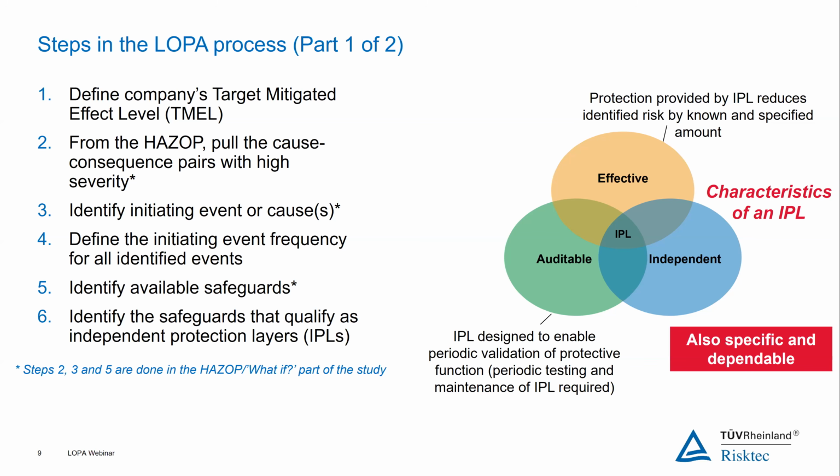Another good example of this is if we're claiming a relief valve, the relief valve has to be suitably sized and rated for the consequence we're talking about. Otherwise, it's not actually an effective control.